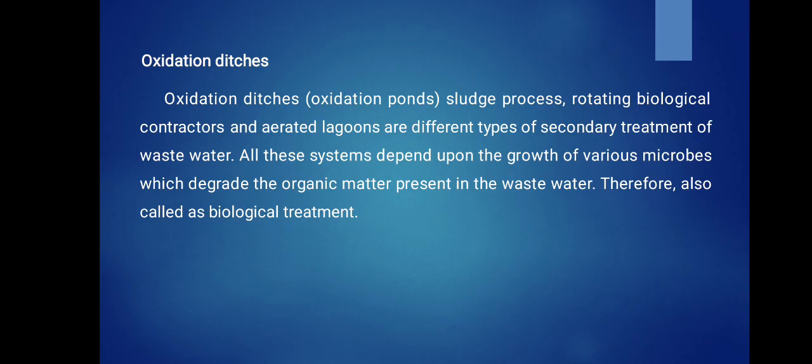is one type of secondary treatment method. Oxidation ditches, rotating biological contactors and aerated lagoons are all types of secondary treatment of wastewater. In all these processes, the growth of microbes is done with the help of atmospheric oxygen.